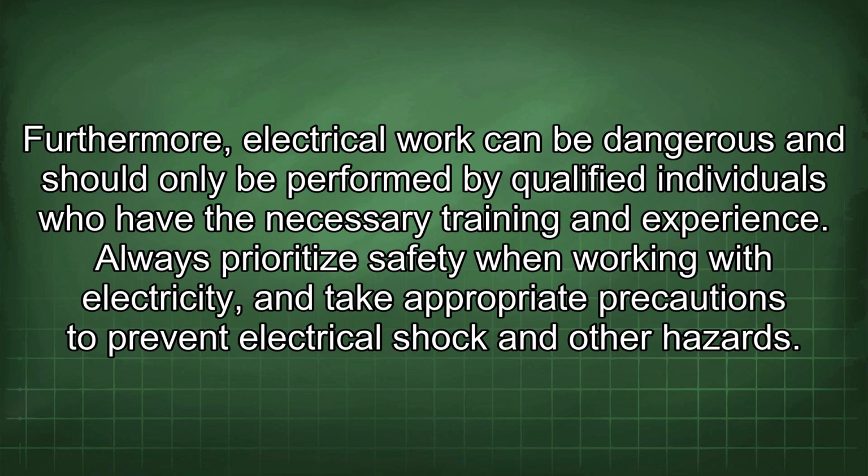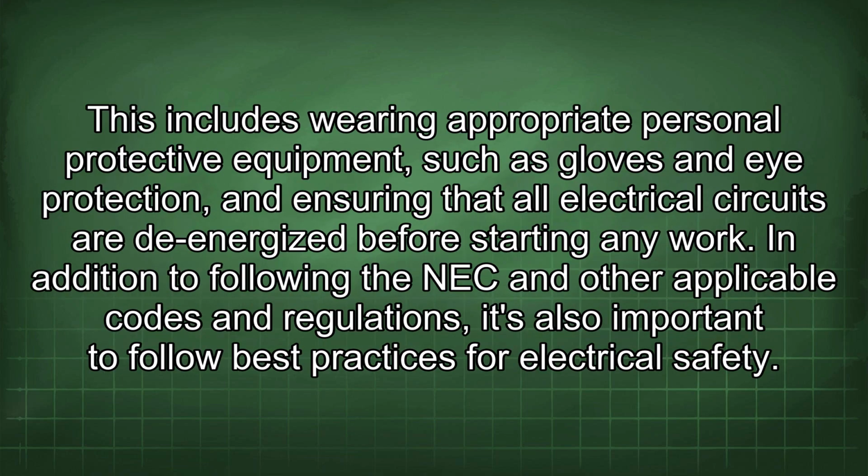Furthermore, electrical work can be dangerous and should only be performed by qualified individuals who have the necessary training and experience. Always prioritize safety when working with electricity, and take appropriate precautions to prevent electrical shock and other hazards. This includes wearing appropriate personal protective equipment, such as gloves and eye protection, and ensuring that all electrical circuits are de-energized before starting any work.